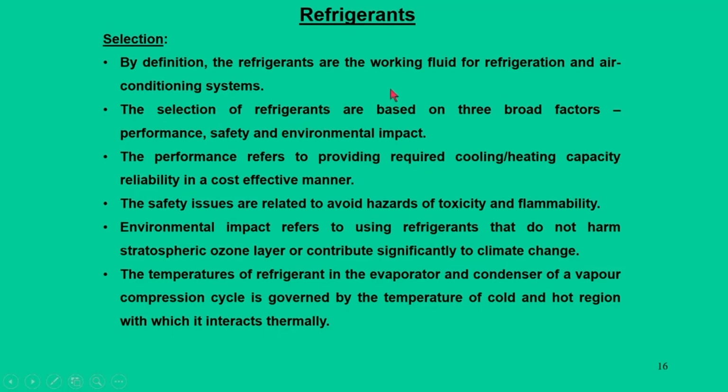So, the selection of refrigerant is very vital, because it is the working fluid for refrigeration and air conditioning applications, and it is based on basically three factors. One is performance, that means we should get the desired effect; another is safety; and it should have minimal environmental impact.